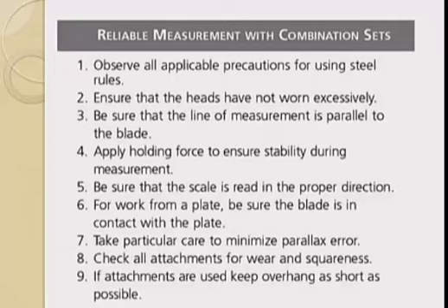Work from a plate. Be sure the blade is in contact with the plate. Take particular care to minimize parallax error. Check all attachments for wear and squareness. If attachments are used, keep overhang as short as possible.